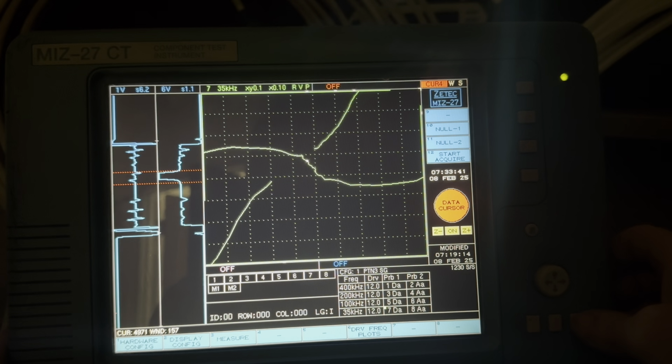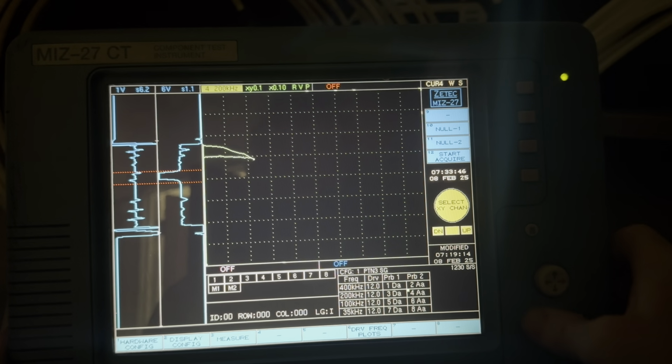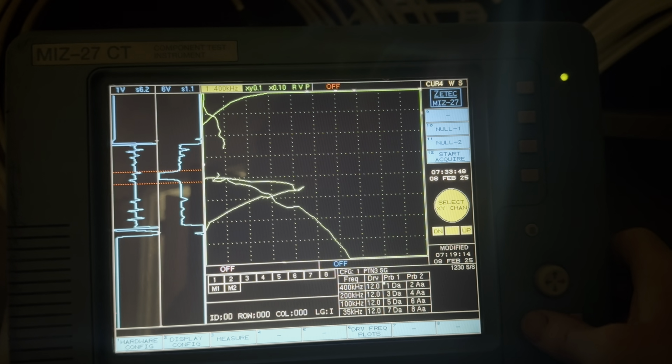So now if I flip over to channel 1, you can see how that's blown way off the screen, because the tube support plate is a big chunk of carbon steel on the outside of the tube that's holding the tube in place. Heat exchangers will have many tube supports, layered throughout the component, and when you assemble the heat exchangers, your tubes will be fed through each one of those holes, and they'll come out on the other end through the opposite side tube sheet. So those tube support plates are good.